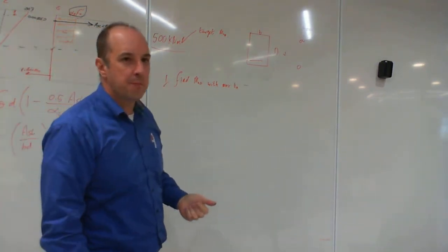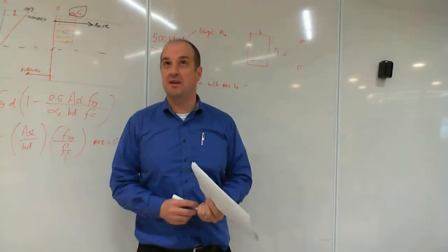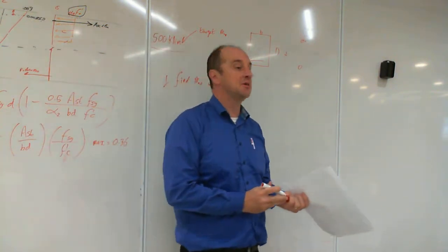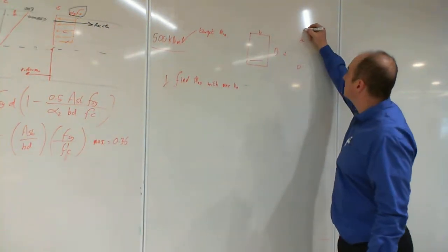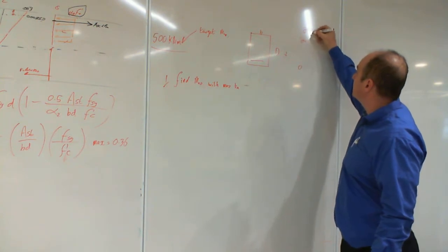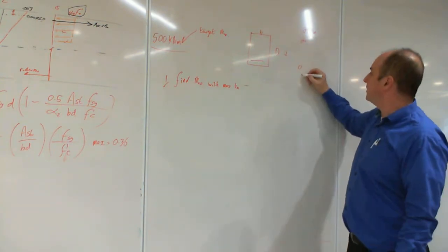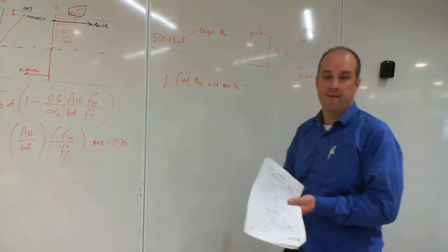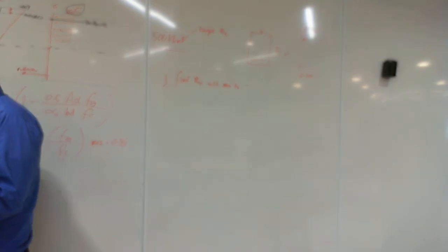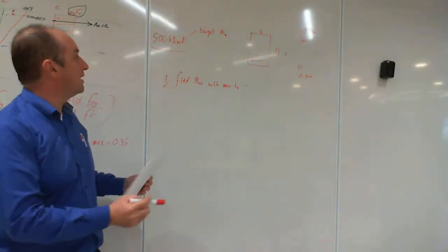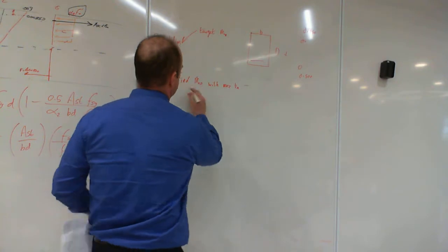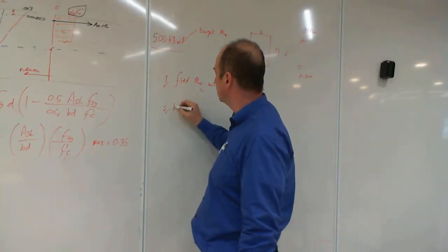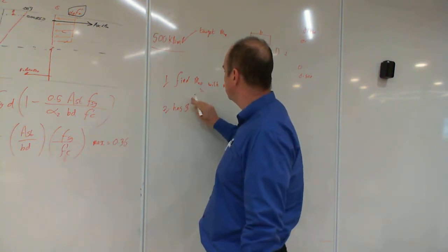When you've done that, then let's say we have a stress, let's pretend it had not yielded, and that our stress in the top steel was 450. So we know our stress there equals 450. And this down the bottom has yielded, so we know our stress there equals 500. Now, that was our target. Sorry, I'm going to say, has the steel yielded? I'll keep up with myself.